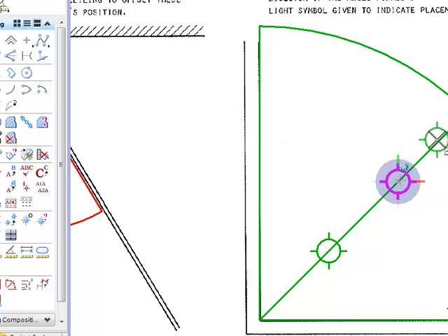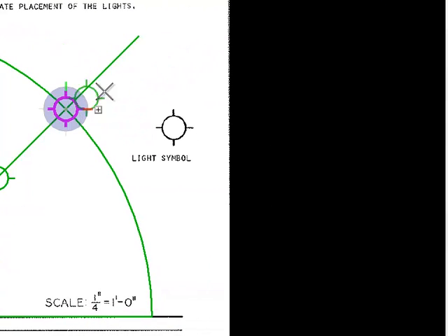And we're going to hit the tab key. We type in 1 again. Tab moves between distance and angle down here. And hit N for nearest. There's the next one.